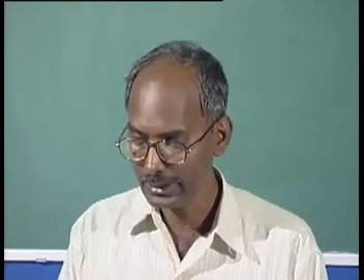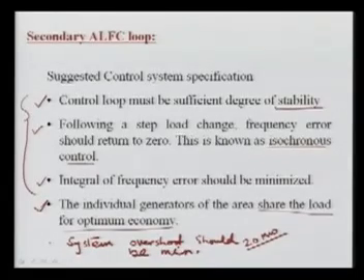Second is the need for frequency constancy. As we noted, if there is a change in the load, the frequency error should return to 0. And this is called isochronous. The term iso is used here; iso means constant, and chronos means time, so it means constant time.